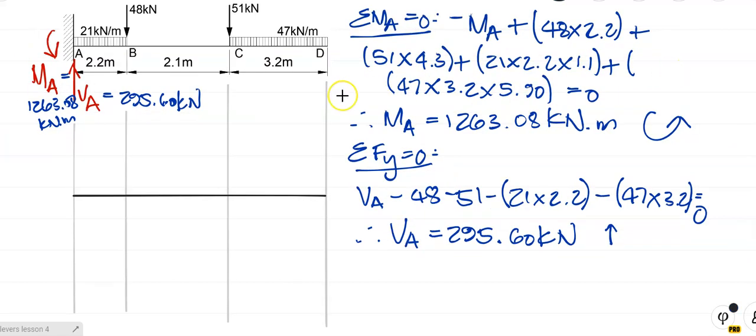Alright, people, I've drawn in my projection lines, where the loads are going to change, and they are vertical and they are parallel. Okay, not any old skew ones. And remember, it's a graph, so to some reasonably good scale. Okay, so there's my shear force diagram. Right, so plus at the top, minus at the bottom.